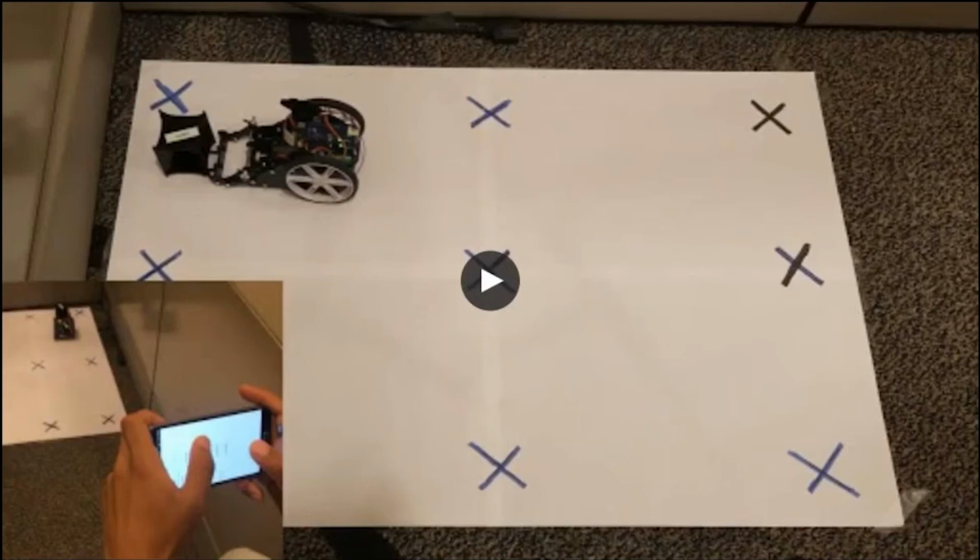Using a minimax algorithm and knowing the status of the matrix, the robot can take a decision on what is the best move. Based on that, the robot will actually go to position, make its mark, and go back home, waiting for the user to do the next move.